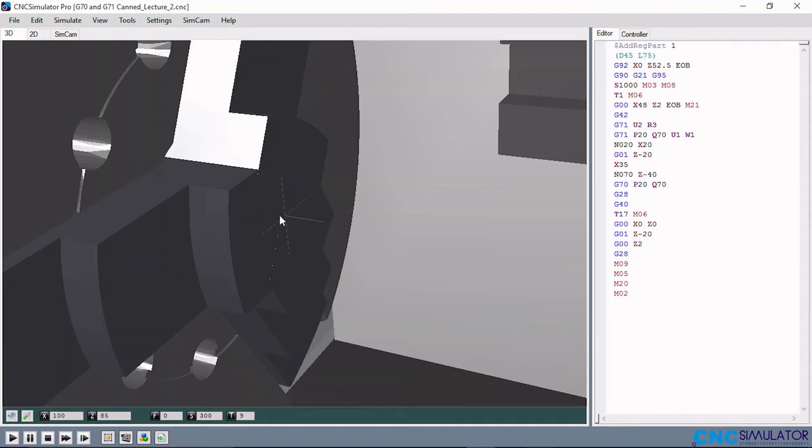And to transfer this origin coordinate from this point to any point on the workpiece, the G code is the G92. So to set the zero offset is G92. Then you need to specify the X coordinate and the Z coordinate.